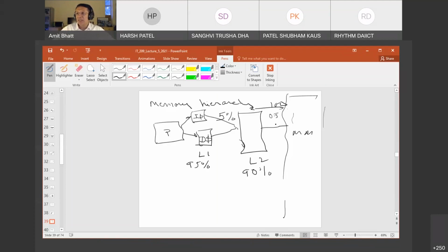But then there are certain applications which are known as real-time applications. And this is important because you may have heard this word a lot of times: real-time processor, real-time operating system, and real-time program. So how do you make a real-time processor? A real-time processor is a processor which is not necessarily faster than your general purpose processor. Your general purpose processor is what you use in your mobile or your laptop or your server. A real-time processor does not have to be faster than that. In fact, most of the real-time processors are slower.